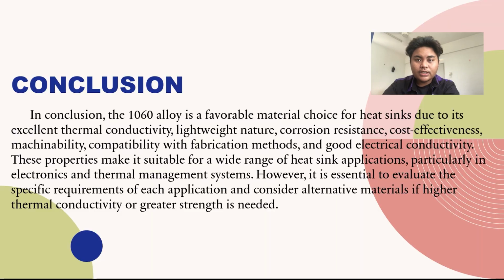In conclusion, the 1060 alloy is a favorable material choice for heat sinks due to its excellent thermal conductivity, lightweight nature, corrosion resistance, cost effectiveness, machinability, compatibility with fabrication methods, and good electrical conductivity.